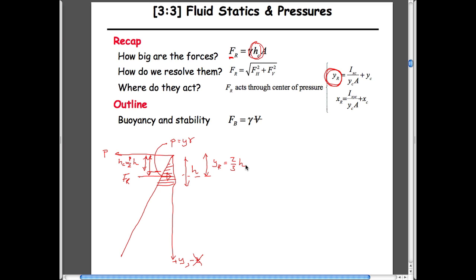screen. So the idea of this is that if I take this and I look for the natural balance point of this pressure distribution, it's 2/3 from the top, 1/3 from the bottom. That's what it is. And so the point where this particular force acts is equal to 2/3 down. Only if it intersects the surface, only if it's a flat, planar structure. As we go down further, I guess I've lost my notes now. My notes are on here, but maybe I can wing it.